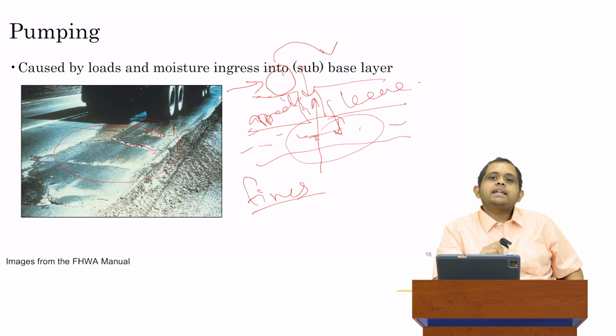That water then can lead to a decrease in the friction. It can lead to a hazard, particularly for vehicles which are driving at a high speed. It can lead to one additional problem: if you have ponding of that water, if that water just stays over there and a large vehicle goes by at high speed, it can cause splashing. And so adjacent vehicles could be splashed, their vision could be impaired, and then they might hit another vehicle in front of them.